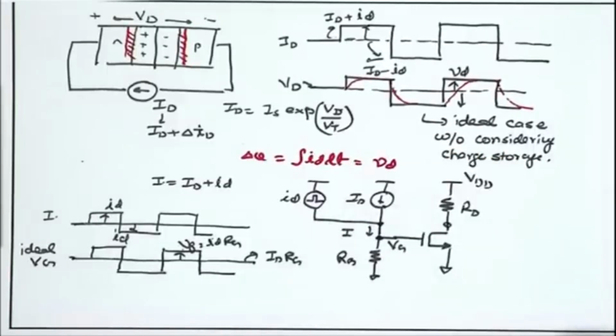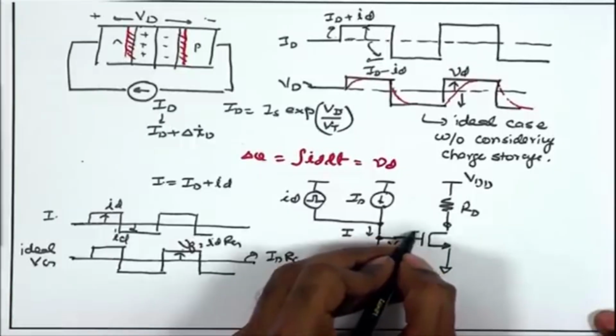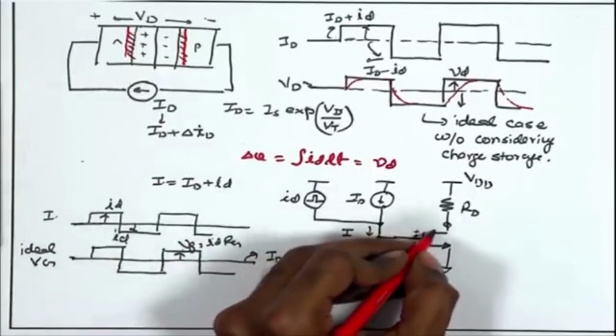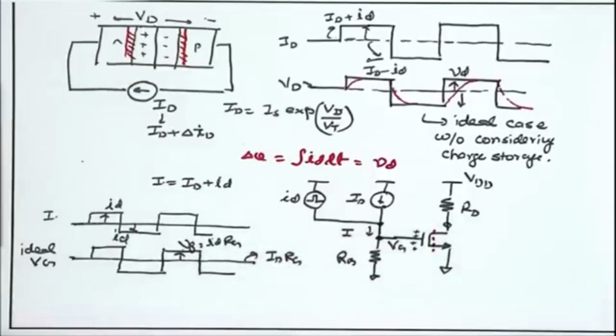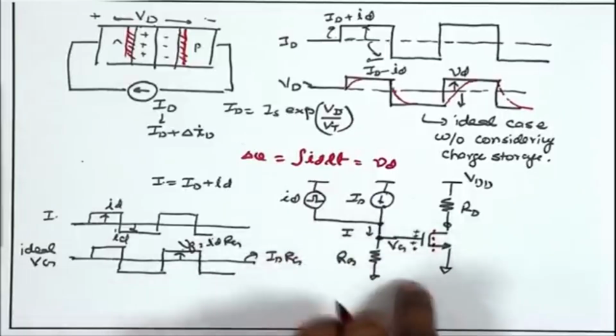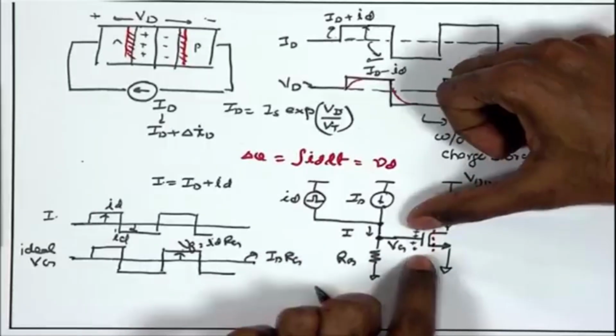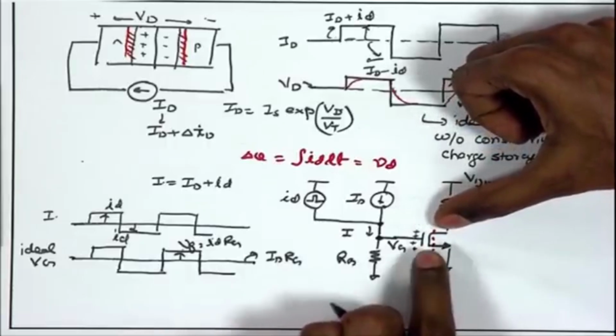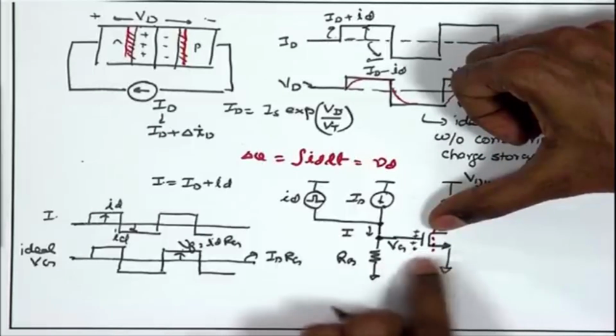But once again, what is going to happen? In order to increase the voltage over here, you are effectively changing the VGS, and whenever you change the VGS, this positive charge must be balanced by an equal amount of additional negative charge in the channel. So, whenever you are trying to increase this gate voltage, it must be compensated by an equal increase of negative charges inside the channel, so that the electric field is once again neutralized.